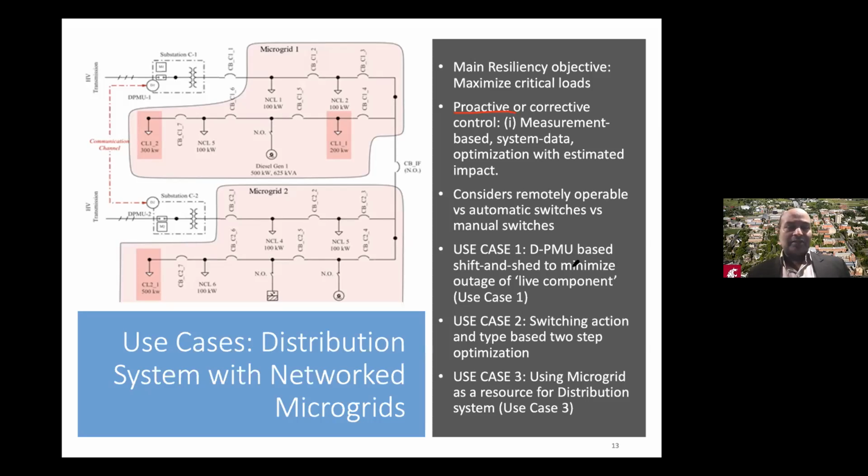Now in transmission grid, we know that would be definitely much more advantageous because of cascading outage that can happen. In distribution grid, cascading outage is not expected because there is no mesh network except in a very small number of cities. So that will not be a problem. But we'll show the results: if we plan in advance to take out those components which are already going to go out because of a weather event, the overall resiliency will be enhanced.